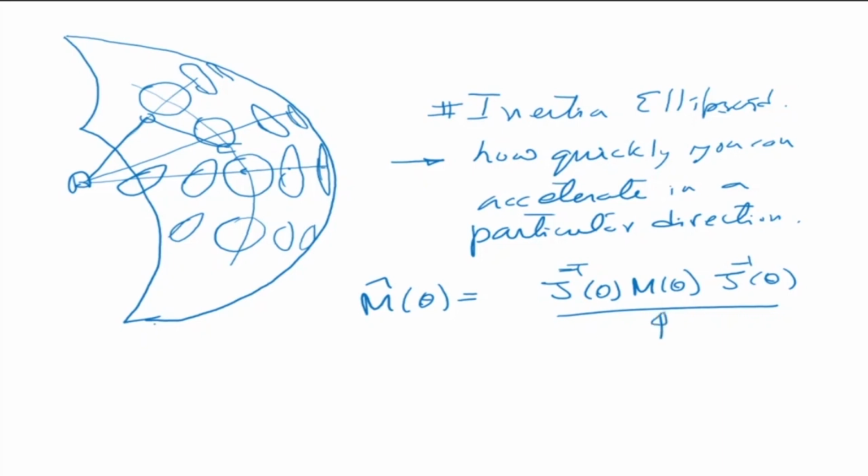You can see that. Okay, so the previous one was not depending on the mass, it was basically a kinematic parameter, whereas this one is more a dynamic parameter, and this indicates directions in space in which you can accelerate. So these are some of the parameters we saw for looking at directions in space where you can have velocity and directions where you can accelerate very, very quickly. Now in well-conditioned workspaces, there will be no singularity inside, and you would be able to move equally well in all directions. Okay, and in this case, we'll have to examine the manipulator from this direction also.